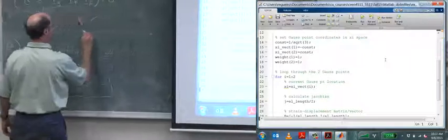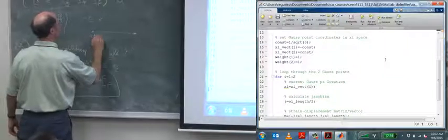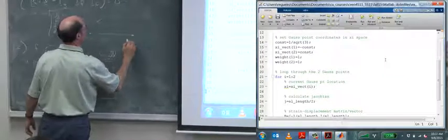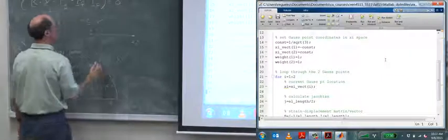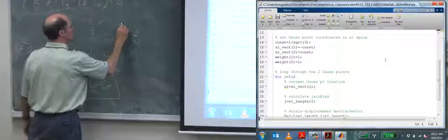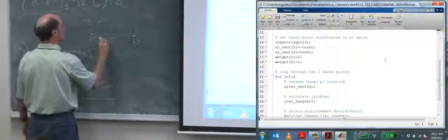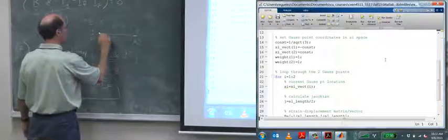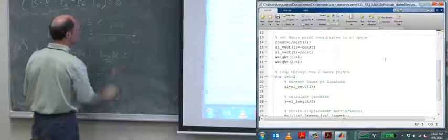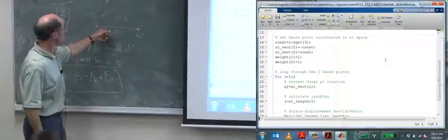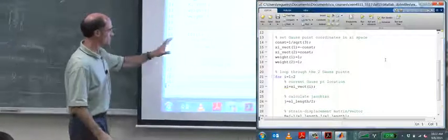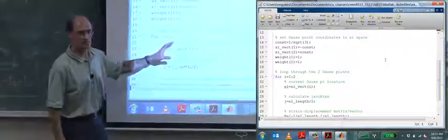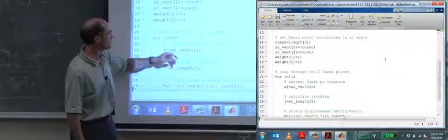So what you're seeing here is that if this is our local element, and this is x1e, this is x2e for element e, and then this is obviously node 1, and this is node 2. Our natural coordinate c is in the middle, and there are 2 Gauss points, or Gaussian quadrature points, one here, one here. This is at minus 1 over root 3. This is at plus 1 over root 3. And the weight of the integration, for those of you who haven't seen this before, don't worry about it. We'll get to this in more detail. But the weights here are just 1.